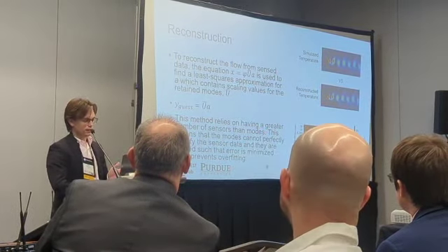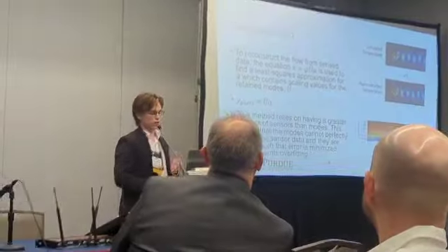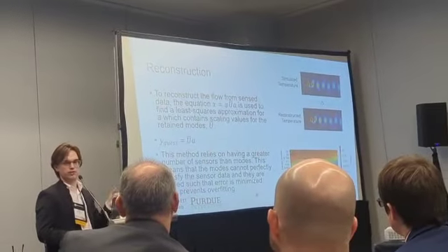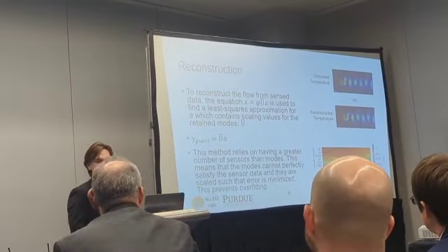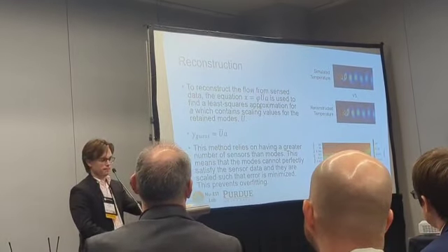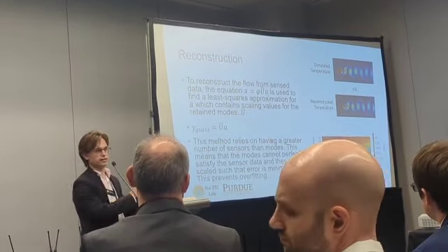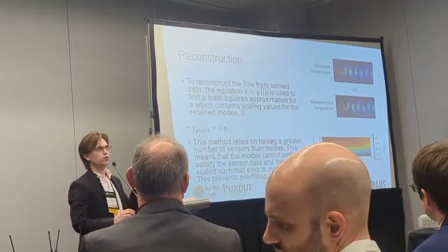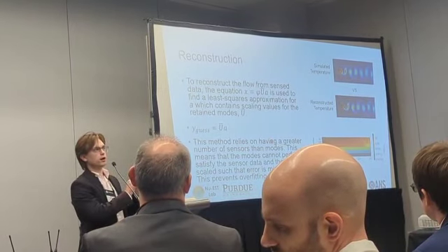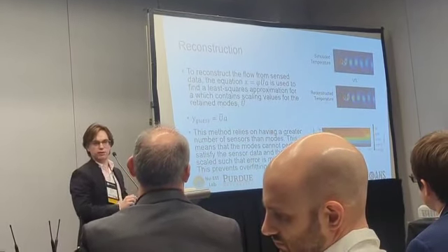Now I note down here, the method I'm using relies on having a greater number of sensors than modes. In mathematical terms, that translates to this matrix algebra representing a system of equations where we have more equations than we have unknowns.